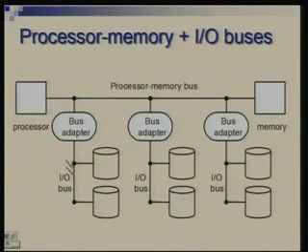The speeds here could be slower, the speed here is fast. Here it is primarily catering for processor and memory, and they occupy the bus mainly. It is only the free slots which may be passed on to I/O for its usage. So this would be more expensive in terms of its design and cost, and this could be comparatively cheaper.